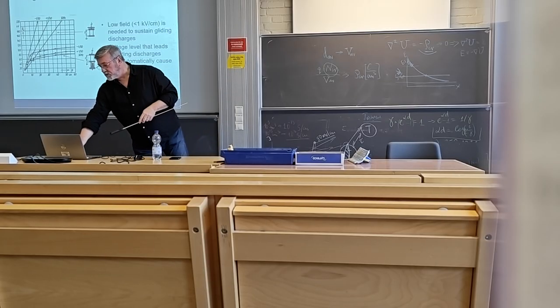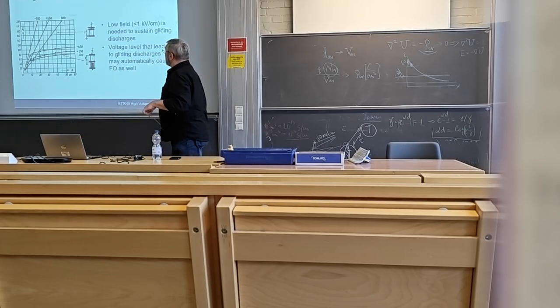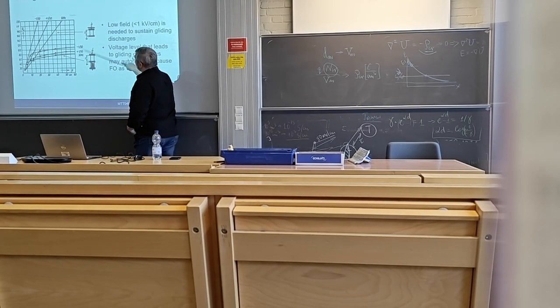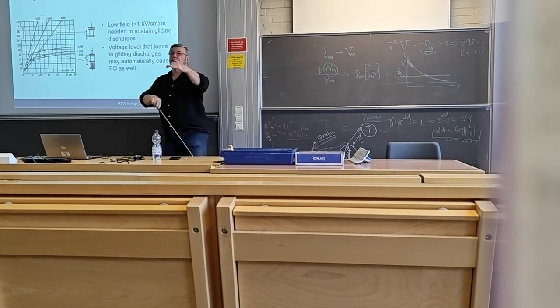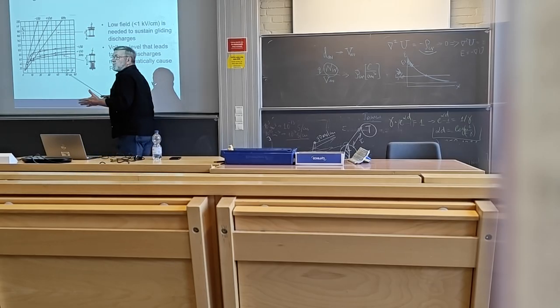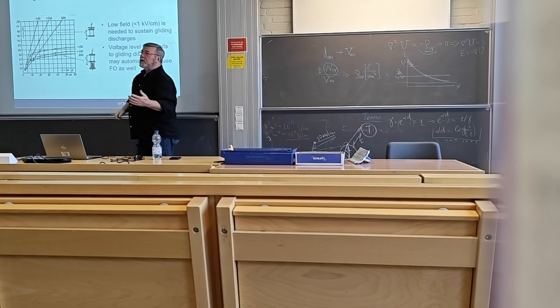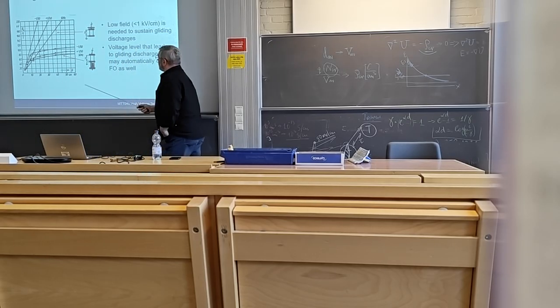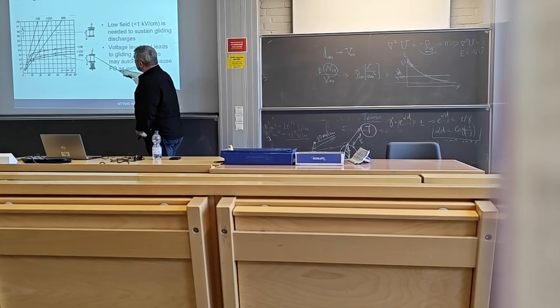So depending on the situation, you may have different conditions. For example here, what will happen? Breakdown voltage as a function of the distance between two electrodes. Between each we have the solid cylinder. Okay? So if it's like that, the larger the distance, the higher the breakdown voltage, right? It's logical. The longer the insulator, the higher the breakdown strength. And this is again 50 Hertz, positive lightning, negative lightning. So very logical.